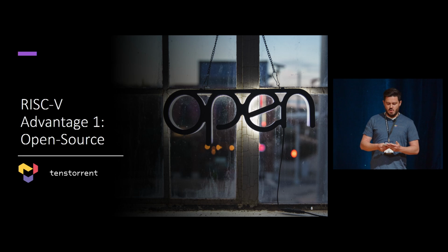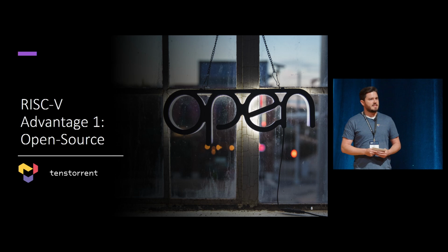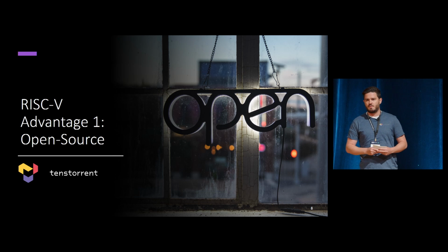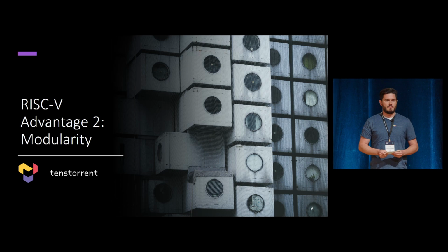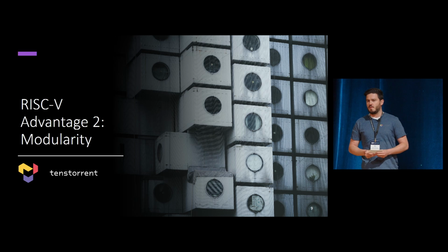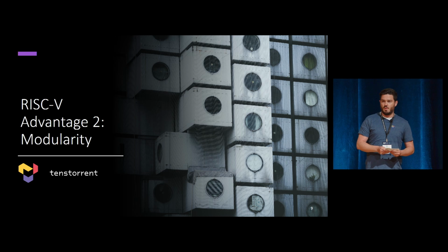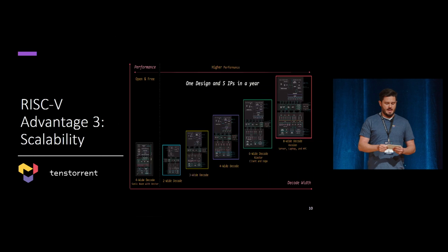RISC-V, while relatively new and basic, is open source, meaning that an expert team can extend it, can add new features, new functionality, and that's exactly what we did. We developed a high-performance design that we can scale from very small to very large. We like it because it's modular. It's composed of a small set of instructions with optional extensions. We've actually added additional vector extensions to the RISC-V base product as part of the RISC-V consortium.